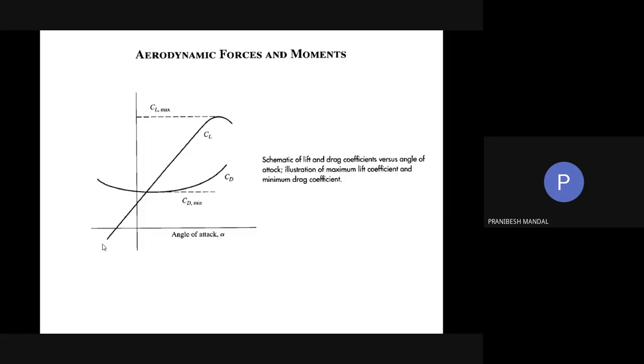So from this particular curve, are you seeing that you cannot actually increase the angle of attack more and more and get the CL to be increased more and more? Up to a certain point that will increase and then this will decrease so rapidly that if we go beyond this sort of angle of attack, it will be very difficult for the pilot to control the airplane at all.